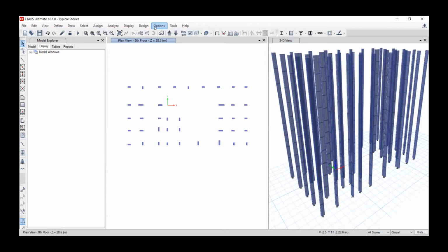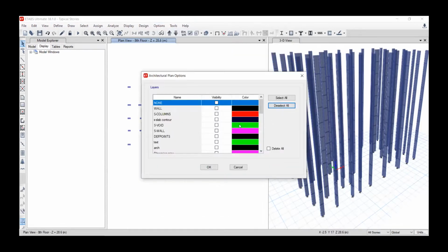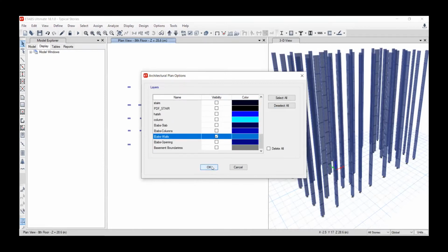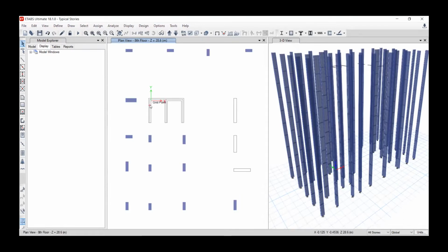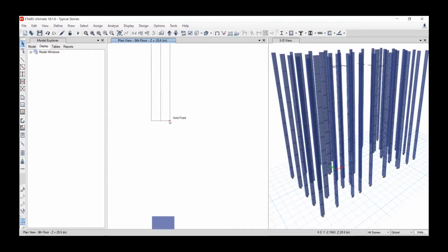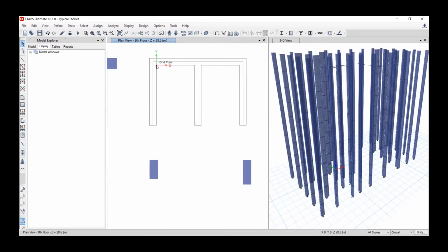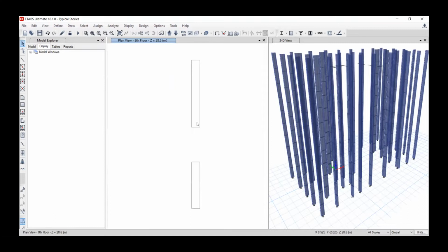Let's continue. We also have an option to see the ETABS walls. Okay, we have the ETABS walls. We need to know the section of each wall. So this one is 0. This one is 0.25, so the thickness here is 0.25. We have here 28.6, and here 0.25 from 0 to 0.25. So all of these are 0.25 meters, 25 centimeters. This one should be, or let me go to see the AutoCAD, maybe I can see it better from AutoCAD.